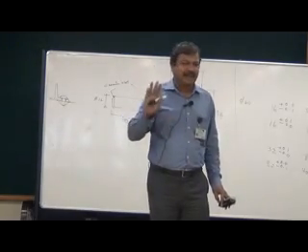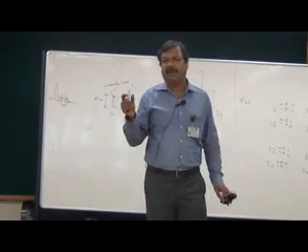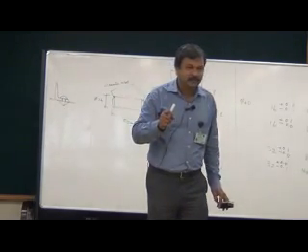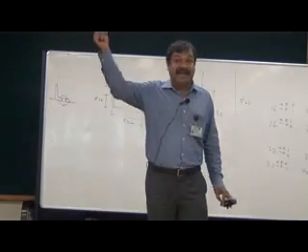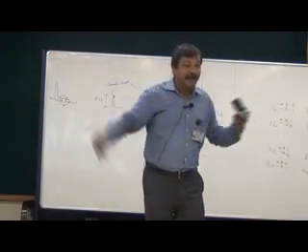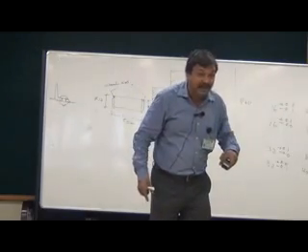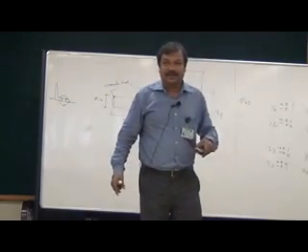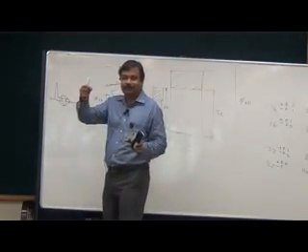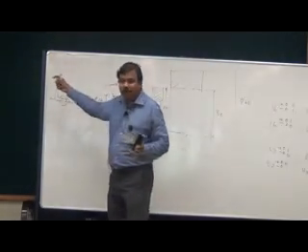All the rivets are kept in liquid nitrogen. They are made of aluminium alloy. I cannot heat the aircraft, it is so huge. But on the other hand, I can cool the rivet. So I take the rivet out of liquid nitrogen and then put it into the hole.